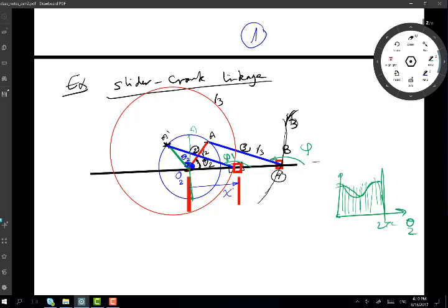However, an interesting observation I can now talk about based on my graphical solution is that this circle with the radius R3 has in fact intersected the ground link, which is this link here, at 2 points, not only one. So I have two possibilities for the slider.